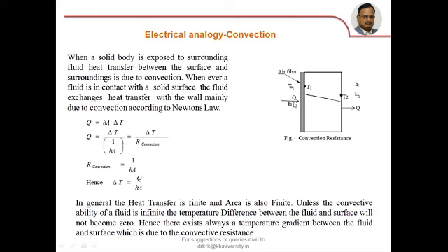So in general, energy can neither be created nor destroyed. The conduction heat transfer through the slab is say Q. That means through this convective film also the heat transfer should be Q only, because only when that Q enters and reaches the surface, it passes through the solid by means of conduction, reaches the surface, and again enters into the environment by means of convection.